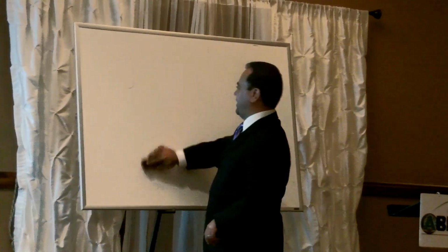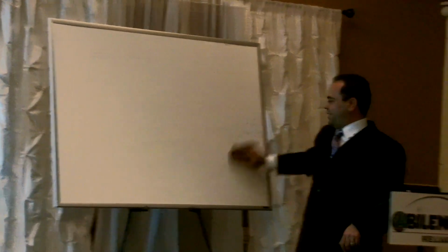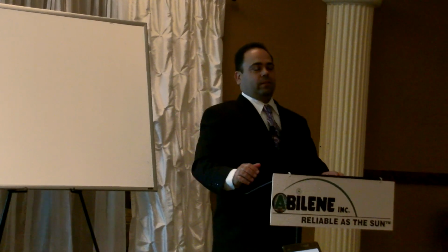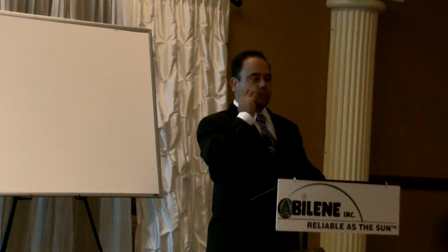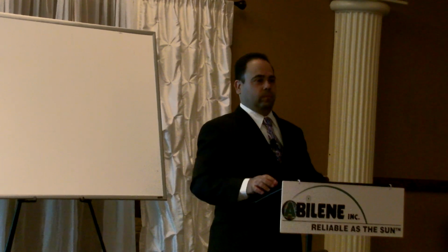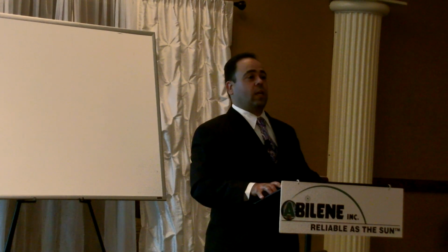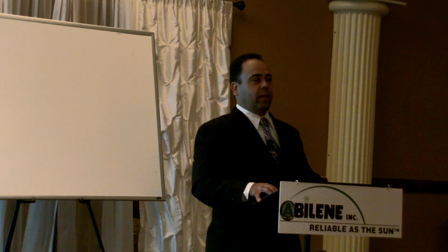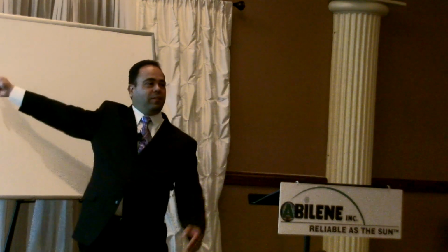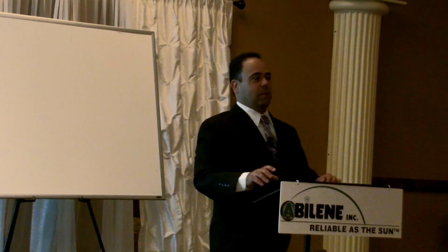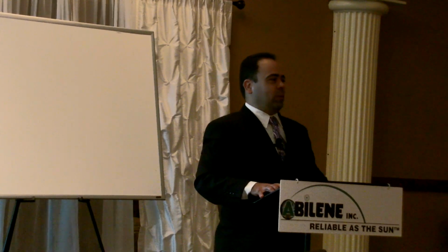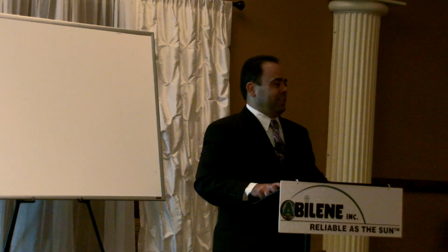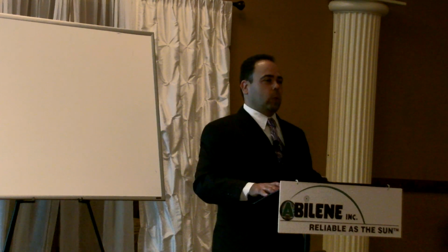Guys, anything? Benny, yes, sir. A question to the electricians, about running the light in the boiler room. Sometimes when they put the light in the back, you're right. We've come across that a lot. The light fixtures, where they get mounted, if they get mounted close to that receiver, it can affect that smoke alarm. And from time to time, somebody leaves the boiler room, shuts the lights off, and then now the thing starts ringing. Because the light is affecting that smoke alarm.